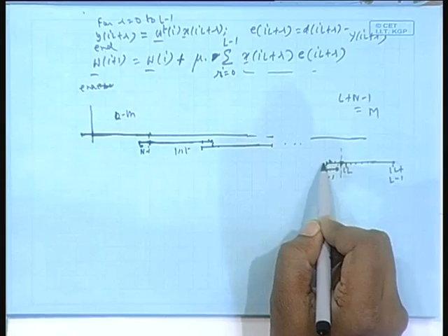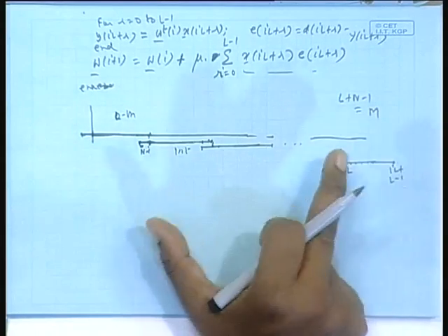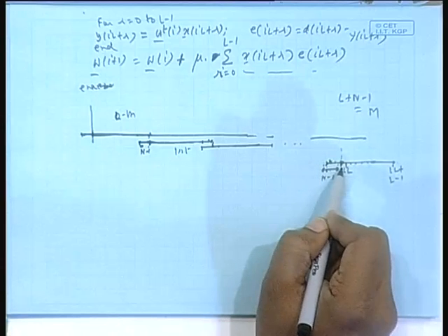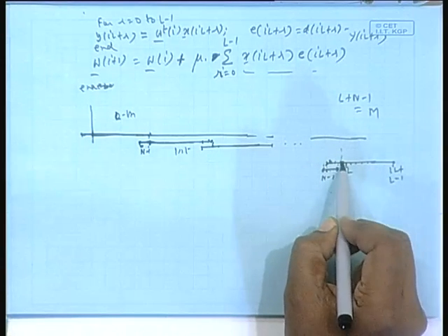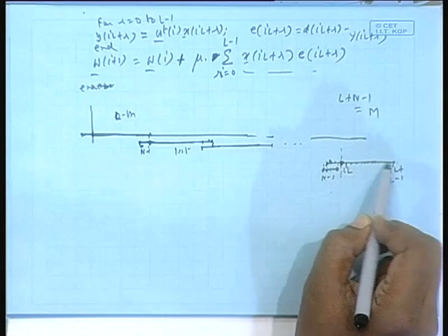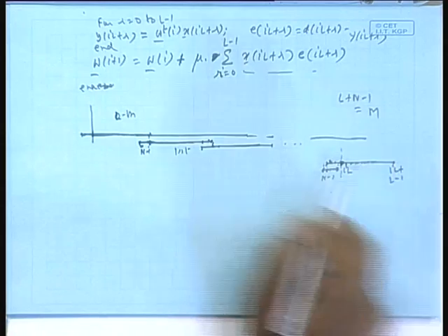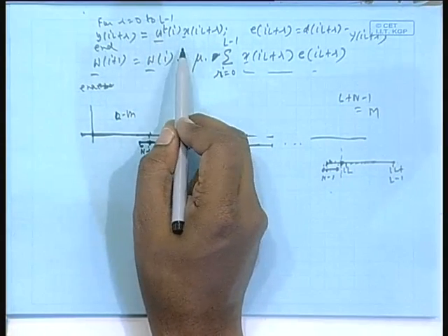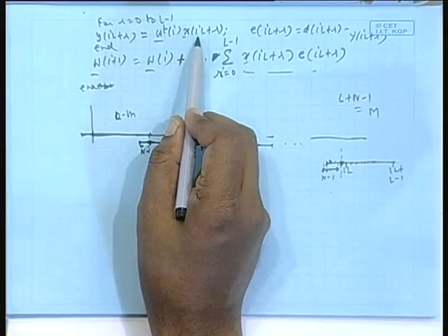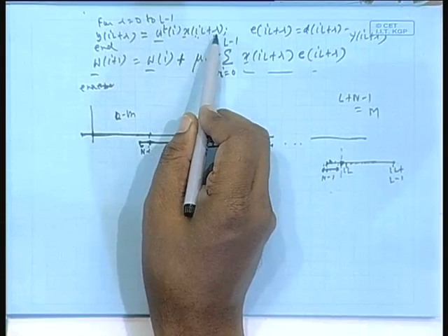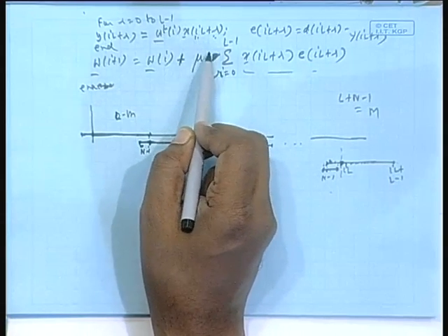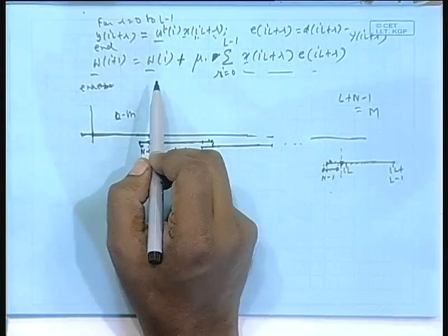it is assuming 0 to the left, whereas this is just part of the continuous data stream. So, the real convolution data to the left of this point would have come in. So, I would have thrown away, and I would get convolution output here, and that is what mathematically is this. Convolution starts at IL plus 0, then IL plus 1, IL plus 2, all these points, convolution output.